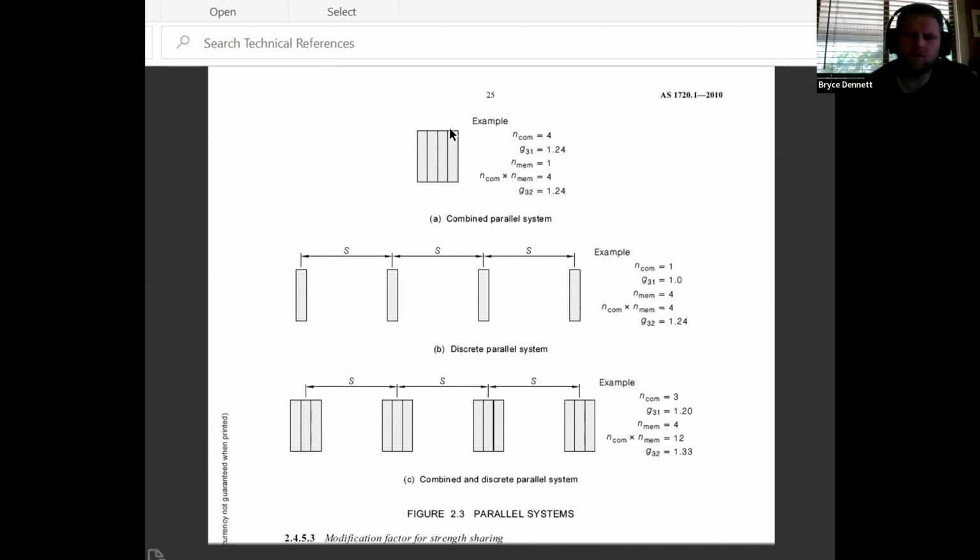What if you put two of those together and have 40? Yeah, well, that's all very nice, but there comes a limit of diminishing returns. So they're saying no. Okay. We've already got all the benefits we can get for you. So it wouldn't end up going up to the maximum of 1.33? No, because they've already built the K9 into it when they give you the strength. Okay. Yeah, fair enough. So you're right. For glulam and LVL, K9, sorry, is always one. So if you double it, you don't get any added benefits. Correct. Just more weight. Yep.